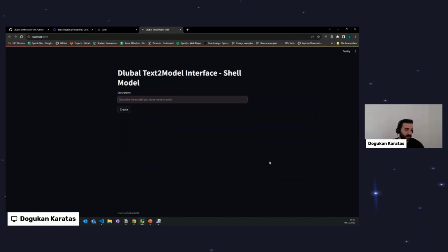Okay, RFEM is open, so I can say, hey, generate a 3 meter by, let's say, 12 meter long shell with, let's select a concrete material, C45/55 as material, and I don't know, 580 thickness starting from origin point 0, 0, 0.